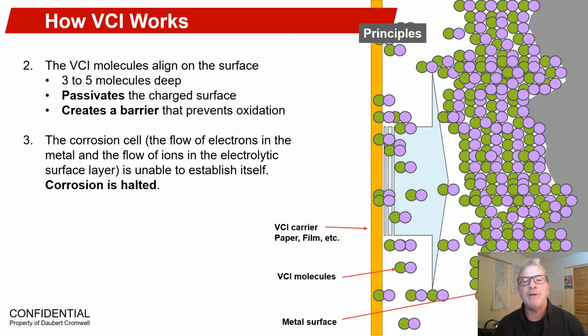Importantly, they do not react negatively with the metal by holding potentially aggressive elements such as moisture or even acid from the paper that's in direct contact with the metal. Poorly designed VCIs can actually cause corrosion if, for example, they are too concentrated or not pH balanced.